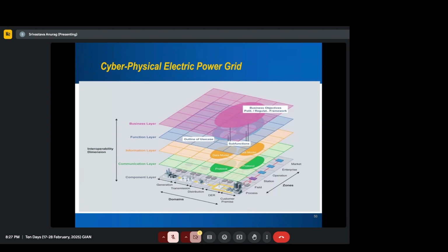And that leads to a multi-layer cyber-physical electric power grid, because that's what we have and we're trying to monitor and control it. We do have a very good management system in transmission, pretty good in generation. Distribution is not fully observed, but we still have a DMS, distribution management system, ADMS. We also have a DR management system, but this whole chain is not much there, right?